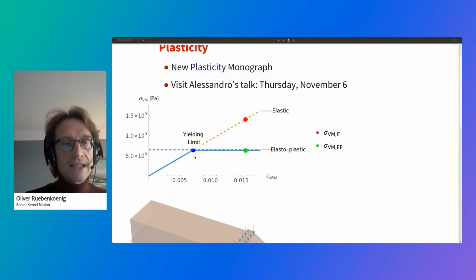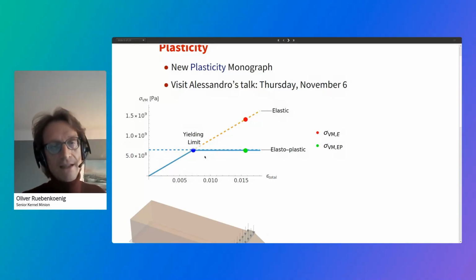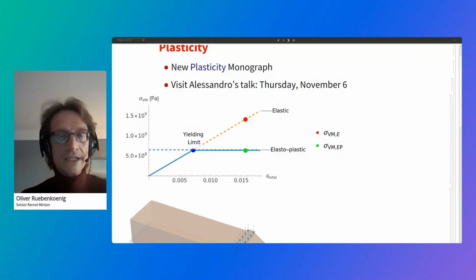So plasticity is a permanent deformation of an object if you bend an object, for example, beyond its yield limit. If you use the standard elastic model, you'll continue endlessly to increase the stress on the object, but that's not the case for plastic deformations. At some point, when you hit the yield limit, the code now needs to go in a completely different branch and compute that an increment of the strain doesn't result in an increment of stress. So that's basically what the yield limit does.